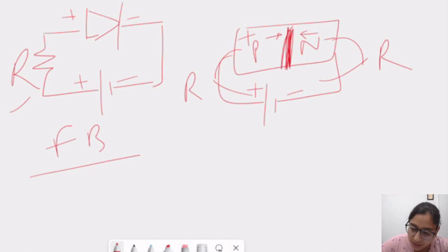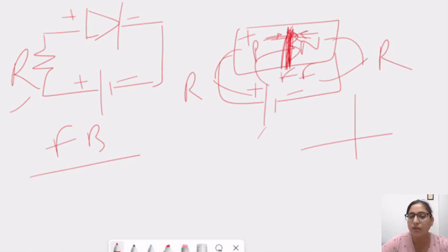If this voltage increases, the electrons and holes try to penetrate this layer, and if they cross the knee voltage, then current will start flowing in a particular direction, which is considered IF. Before the knee voltage, the current is negligible, and after the knee voltage, the current increases exponentially.